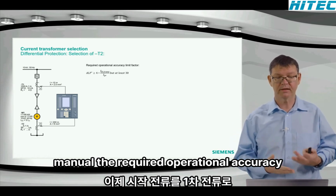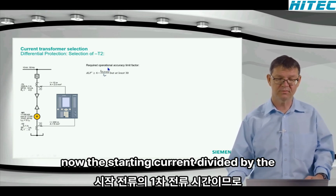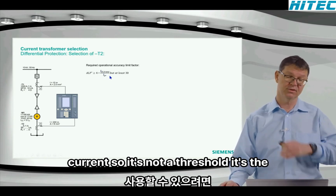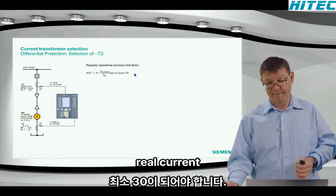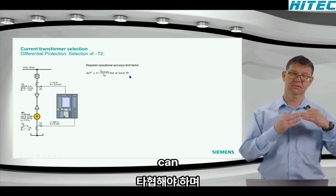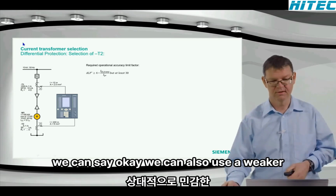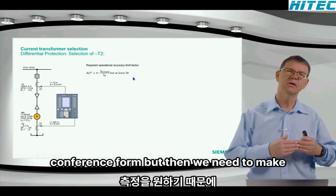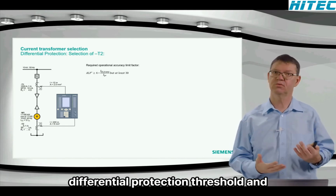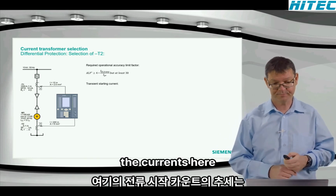The required operational accuracy limiting factor is now the starting current divided by the primary current times 4, the transient starting current divided by the primary current. So it's not a threshold, it's the real current. And also here, we say it must be at least 30 so that we can securely use our sensitive threshold here. So we can say, okay, we can also use a weaker current transformer, but then we need to make a compromise and we need to raise our differential protection threshold. And this is not really what we want, because we want to measure the currents relatively sensitively here.